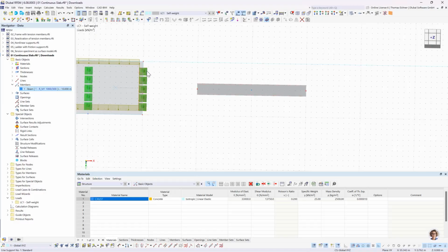This is not possible with this line hinge for the surface, since let's say supported here and here, so no rotation is possible. But with this point nodal support, we don't have this interaction kind of. So we need to also restrain this rotational degree of freedom.